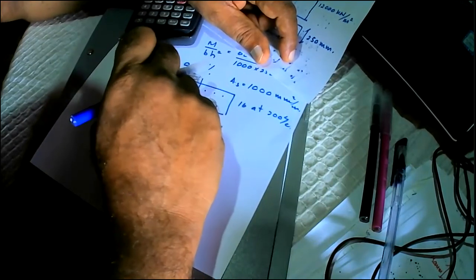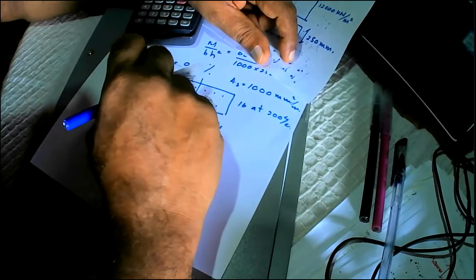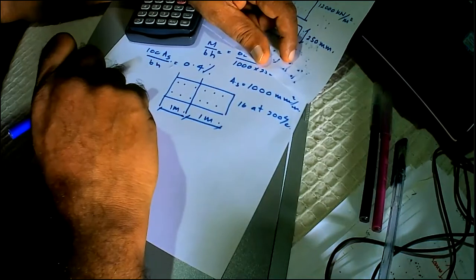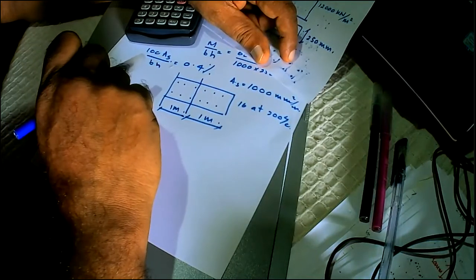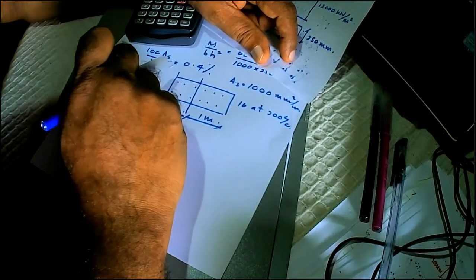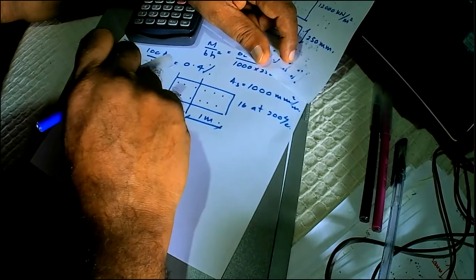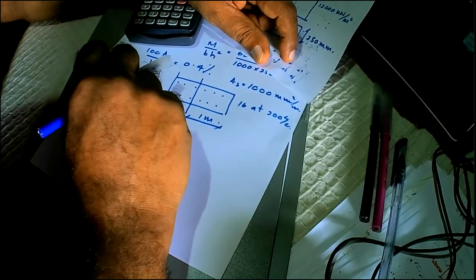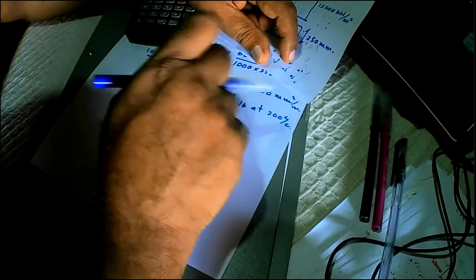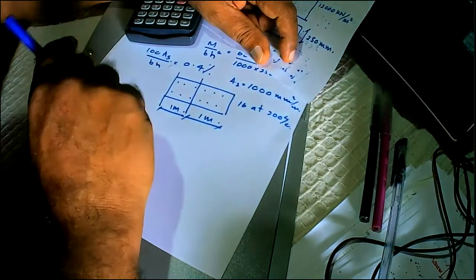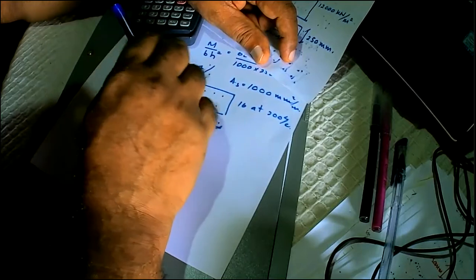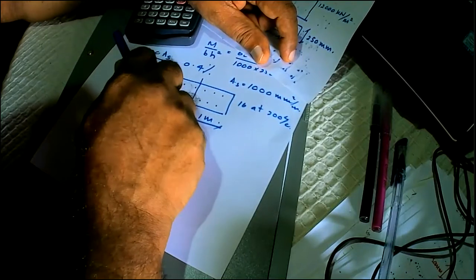So there are two different methods of finding the reinforcement, and I have used the BS 8110 column design chart, but for Eurocodes also you get column design charts where the equation is slightly different, because what we find is N over b h fcu, fck, something like that. So basically the method is the same, and if you know the overall moment and the axial load, you can find the reinforcement, considering it as a column.